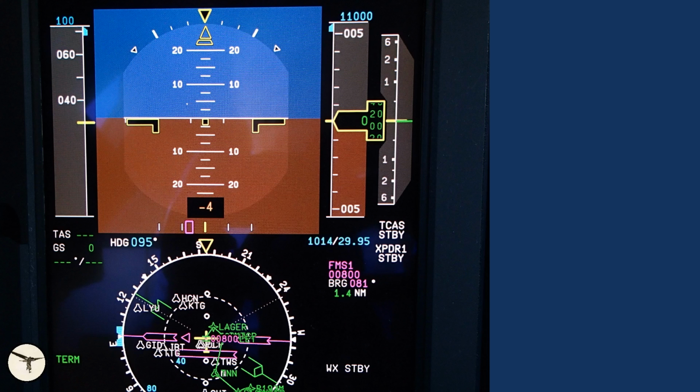This hack is for ATR aircraft with glass cockpit. The barometric reference pressure for the altimeter can be set in hectopascal or inches of mercury. A difference in 1 hectopascal represents 28 feet. A difference in 0.01 inches of mercury represents 10 feet. So when the altimeter setting is 1010 hectopascal, it can be from 29.82 to 29.84 inches of mercury.